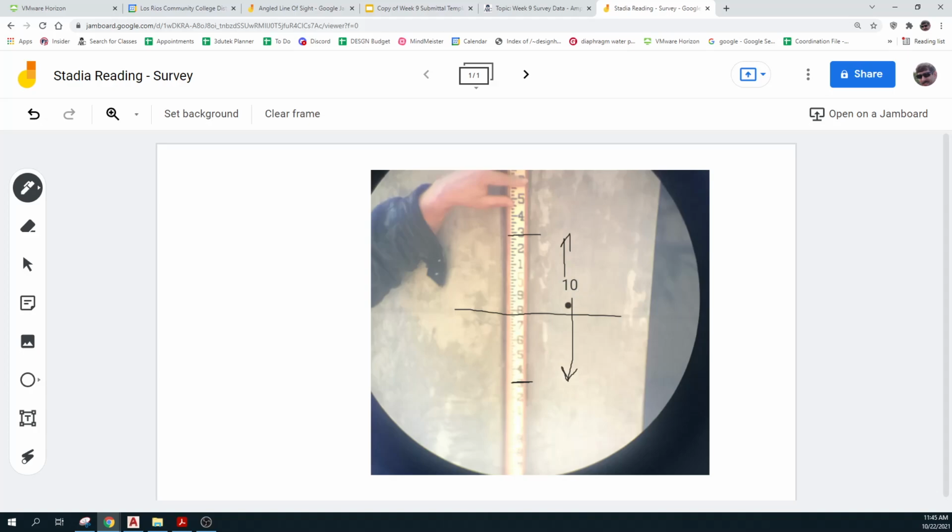That's cool. Okay, and these are decimal feet, right? So that's 0.1 times 1,000. So you could actually just count those out and then multiply by 10, right? 10 times, they call it the stadia factor, 10 equals 100. And that's how many feet it was.